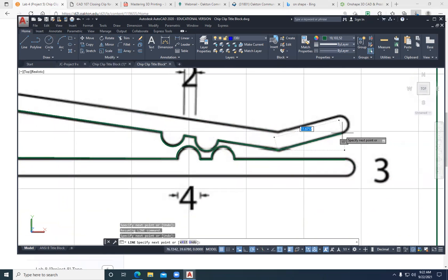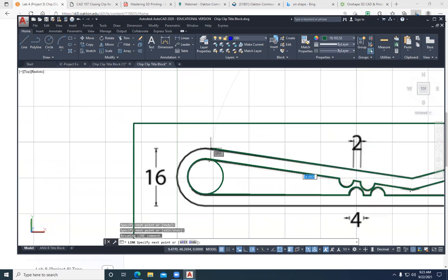And so as I went through and made these projects up for you guys, I want to introduce some technique for it. And then we'll come back here. You could use a polyline on this, and it's a good idea to soften up the radiuses at the corners because those tend to break.